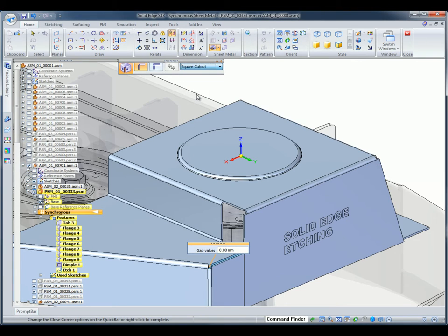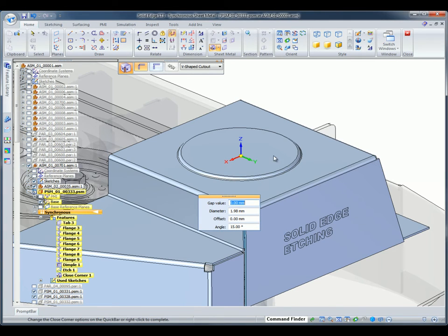We've also enhanced our corner reliefs. We now have the ability to add a square, a U-shaped, a V-shaped, or also a miter corner inside of there. If your corners do not actually match up or together, they're spaced out, no problem with Solid Edge sheet metal. You can simply go in, we bring those two together, give you a watertight corner, and you can again choose what type of corner relief you would like to see in that corner.